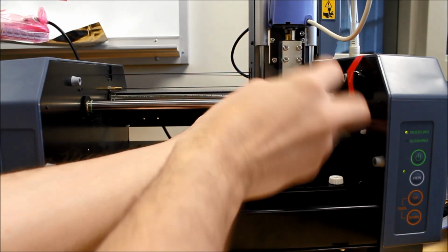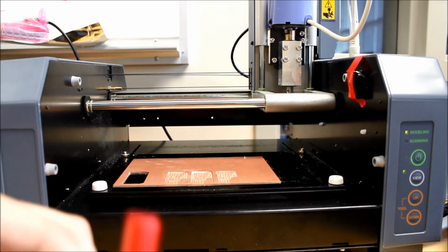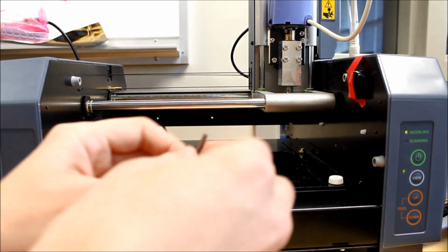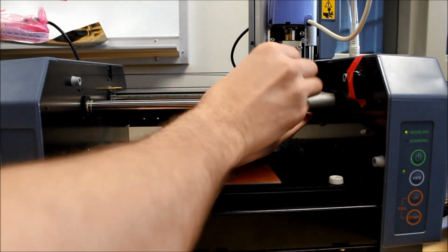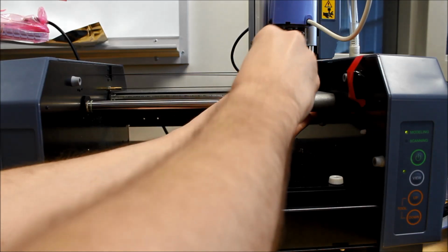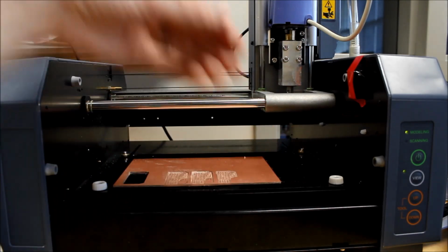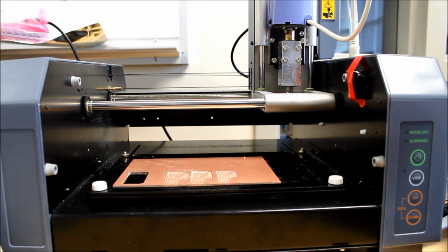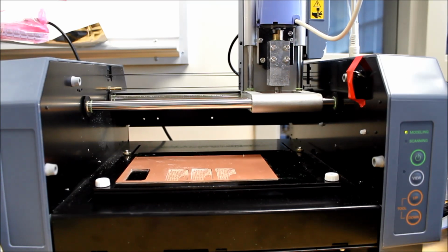So I'm removing this bit, replacing it in the tube, and I'm going to put in the other bit. And again, I'm going to have about 1.25 inches or so sticking out the bottom. I want to have some room for the bit to drop down whenever I get it set back up. Turn the machine back on, and take it out of view mode.